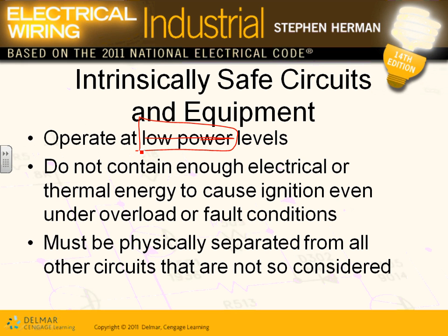Like for example, you can put an intrinsically safe system in an EMT conduit, but you can't put a power circuit into an EMT conduit in a rigid location. You have to put it in rigid conduit in a Class 1 Division 1 location.